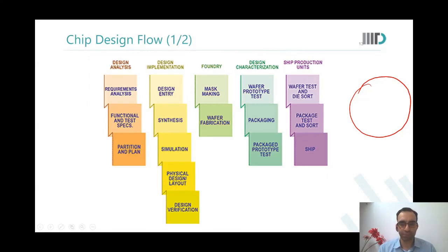Yeah, because the thing is, you can do die sort right after the package prototype test. So, no, I don't see why you need to do a wafer test. Meher, if you've already packaged it, then there is no longer die sort, then there is package sort.